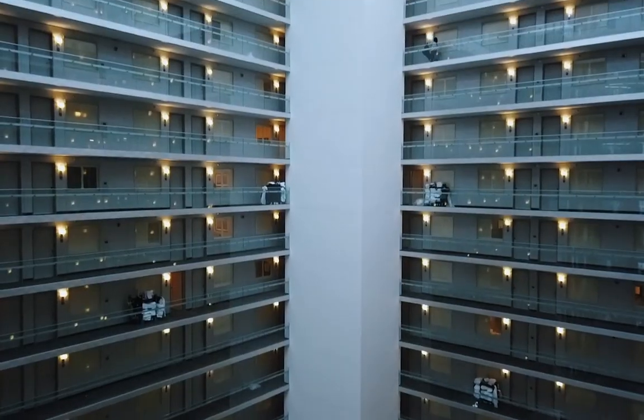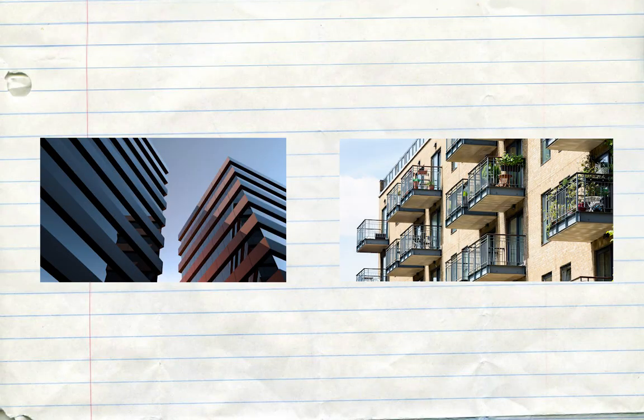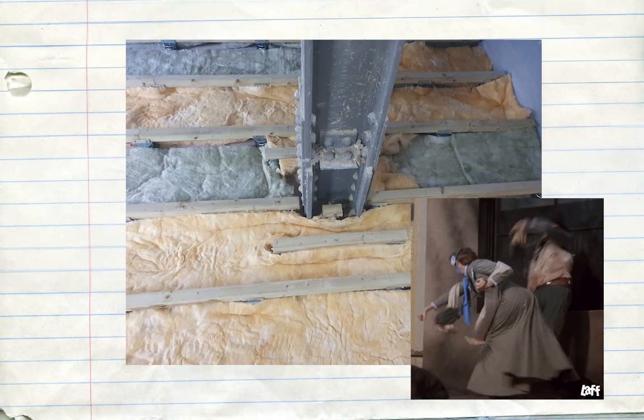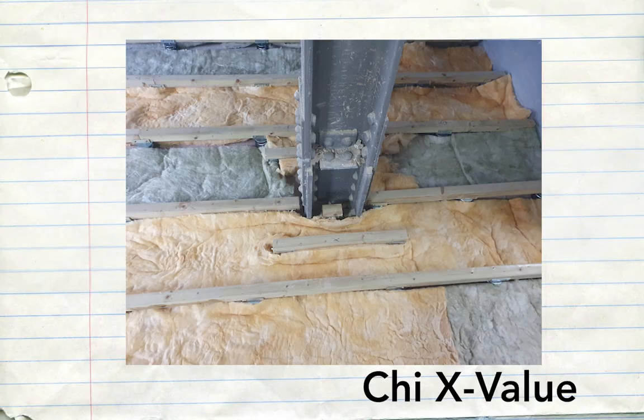Now, there are two main types: linear thermal bridges, which are found along the length of balconies or corners, for example. We measure this with psi value. This one is also divided in two groups. Geometric, that's when the shape changes dramatically, like a 60-degree turn. Constructional, when insulation is penetrated and standard calculations just don't cut it. And there are point thermal bridges, like a column punching through the floor. Now these are 3D and measured using chi value.